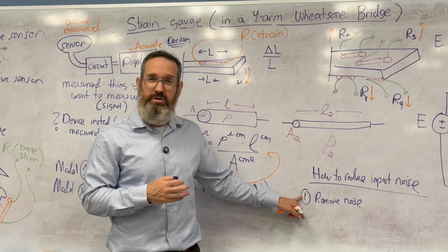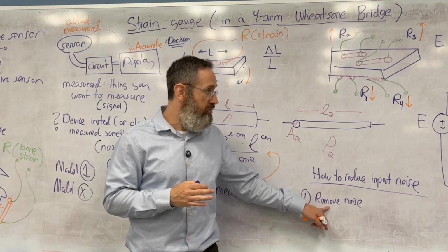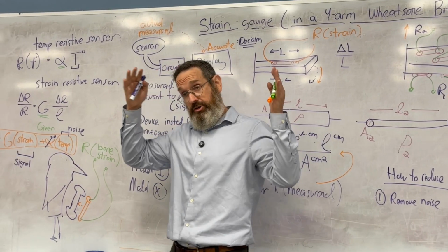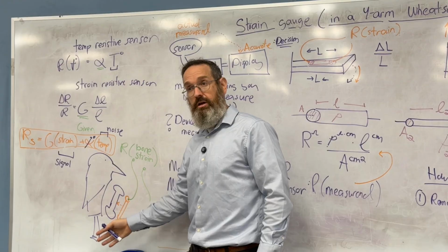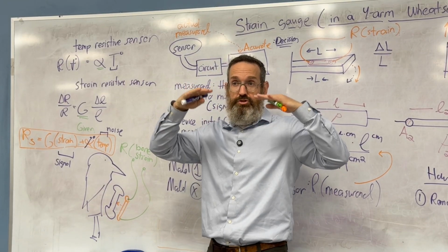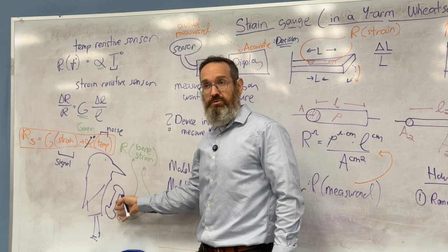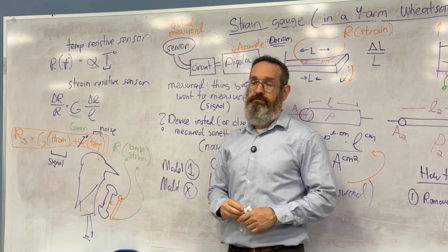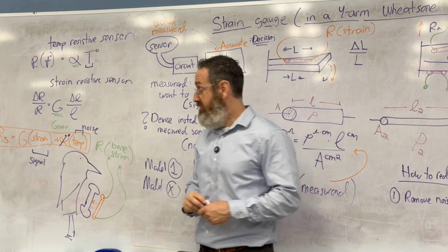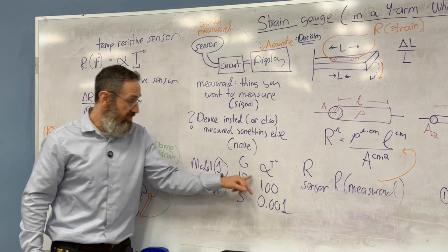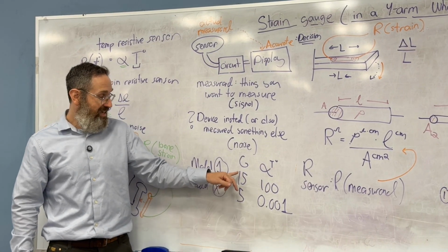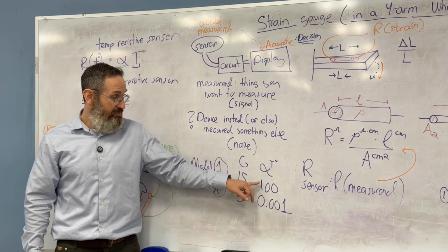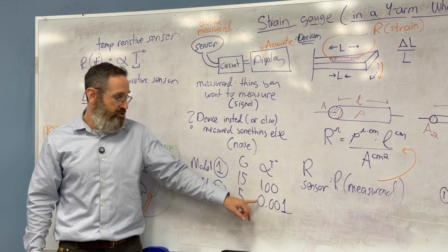But your point of, and I think your question was, if we remove it, do we remove the signal? Well, no. Like in this case, if our chicken coop now had air conditioning, well then we would remove the influence of temperature, but the strain would not be removed. My question is more like in terms of the material components of the sensor itself, by changing the alpha. Oh, but right, your question about the materials, correct. The difference between these are materials. So in this case, a material was chosen with a decent gauge factor, but this material here is very sensitive to temperature and this is not.